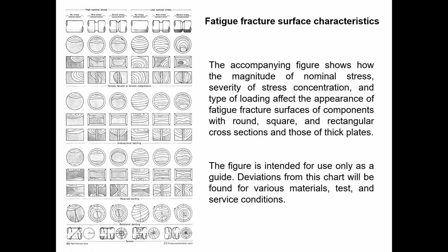In both of them there is both ductile and brittle failure. So this is a combination of ductile and brittle failure. But in here, significant failure will happen due to ductile. We can say that. You can see there's a shade area; the shade area is due to brittle. You can see the contour lines; those contours are due to ductile. And the shade area is significantly larger than the contour area.